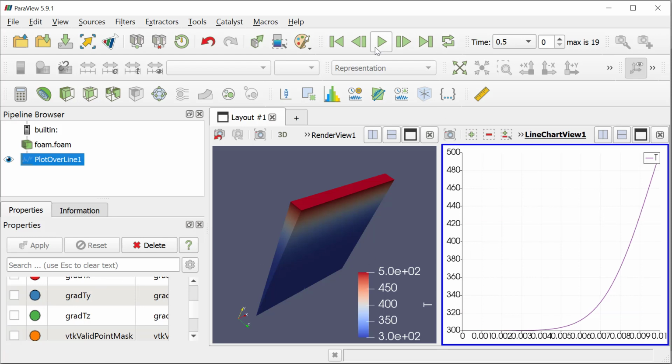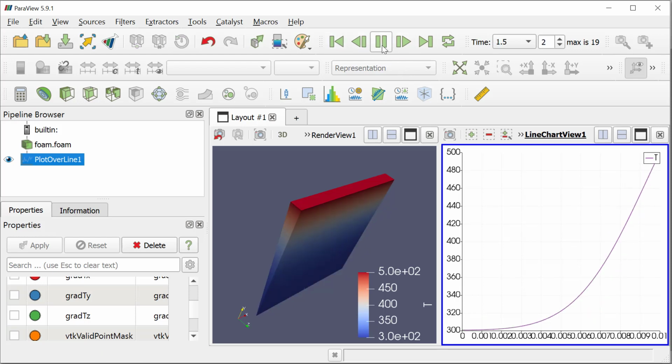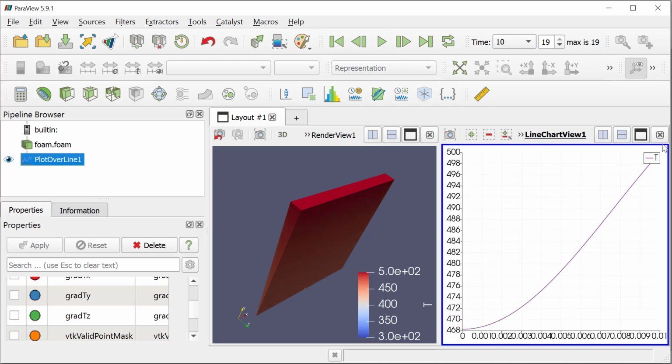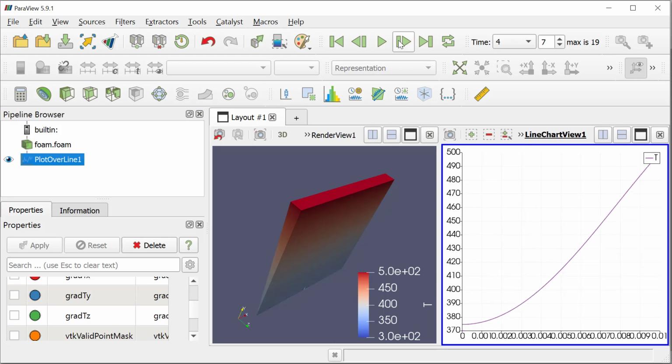So there's my temperature, and as I go through that, I can see it rising up slowly in the center. As we would expect, eventually that new boundary condition bleeds over into the center, so at time equals 0.5 seconds, this very center of the rod has not felt the effects of my new boundary condition, but by 1 second you can see that it's already started to feel the effect of that. Now I'm at 300.8, and then it just continues to rise after that.